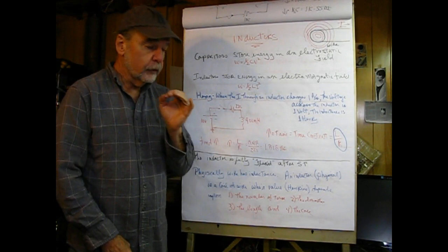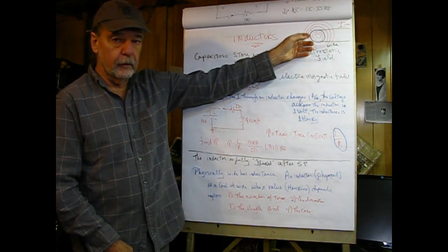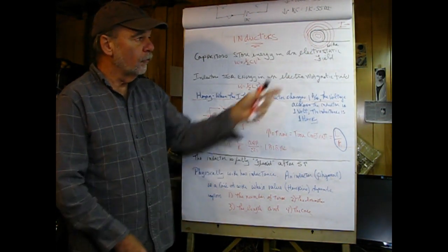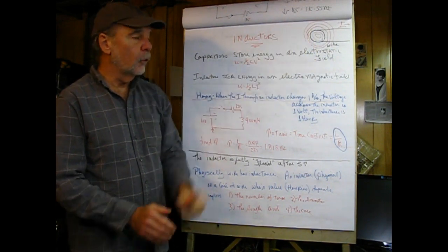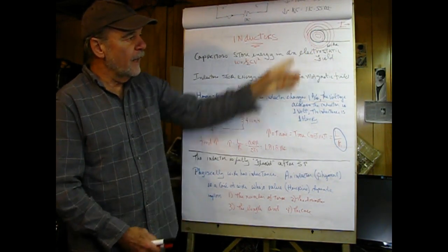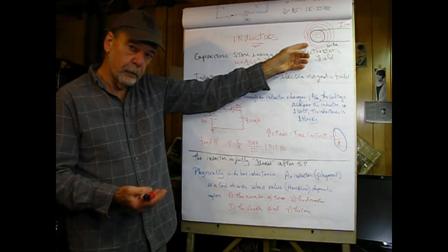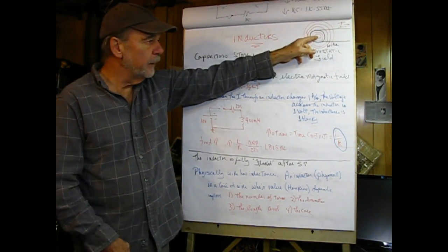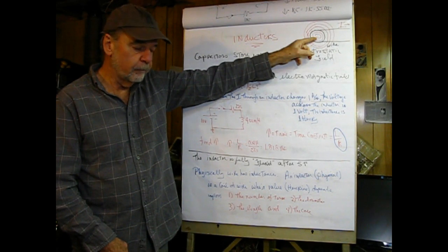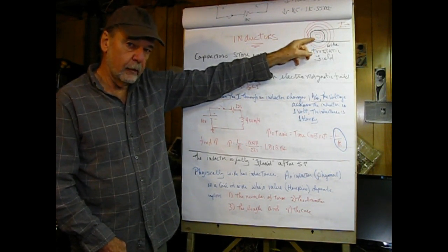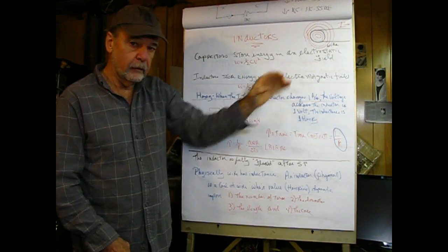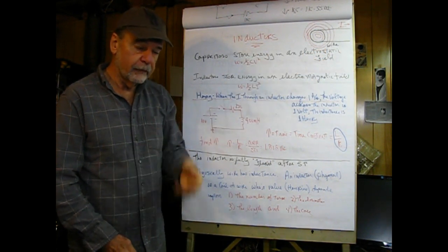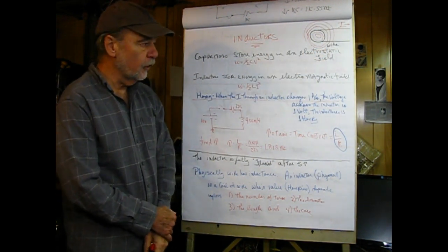If the wire is perfectly circular, at the very center of this, a magnetic field, an H field of concentric lines, will begin and grow first inside of the wire and then external to the wire. The size of the magnetic field is determined by the current flow through the wire. Starting on the inside of the wire may not seem eventful, but at high frequencies the effective cross-sectional area of the wire decreases because current is impeded in the center of the wire due to the magnetic flux. That's a topic for later on, but I thought I'd mention it going into this.